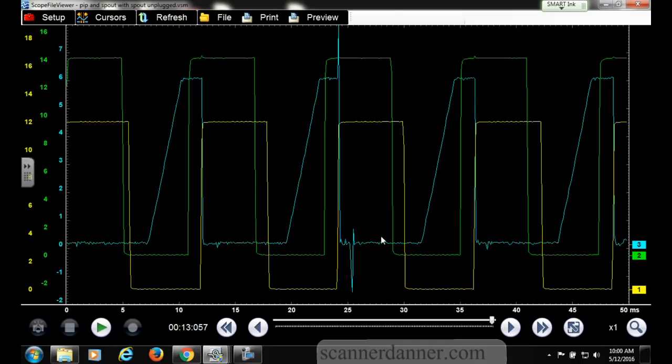Can you see it? So every single time that this PIP signal is increasing is the same time that we're taking this coil current ramp pattern, our ignition coil primary circuit, and we're turning it off.